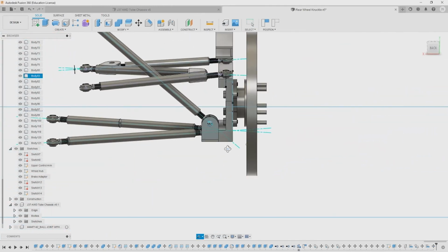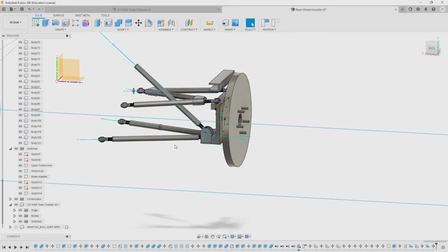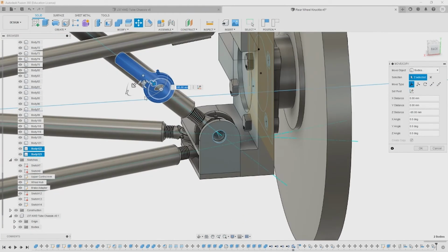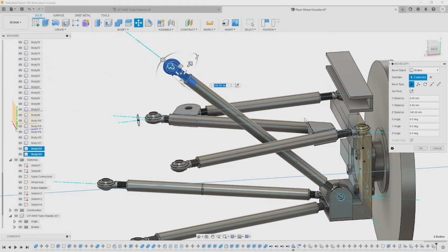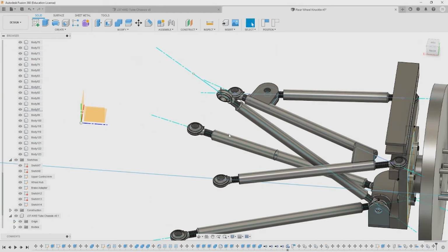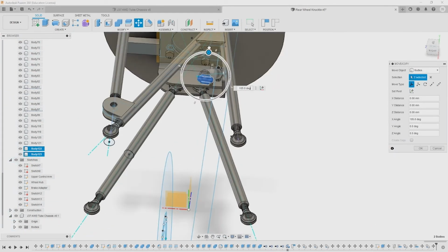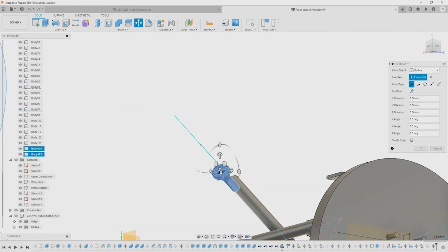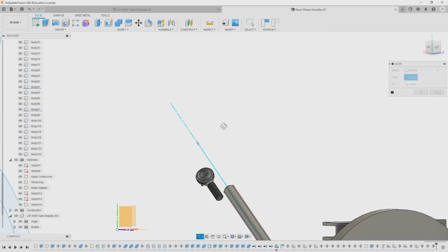So next week, I'm going to be building my first rocker on the top, and that is going to be what connects that arm that's going up at approximately 45 degrees to the motion or location of the coilover. They have to make approximately a 90-degree change, and so the rocker on a bearing is really the way that we fix that. So next week you'll be able to see that if you tune in.